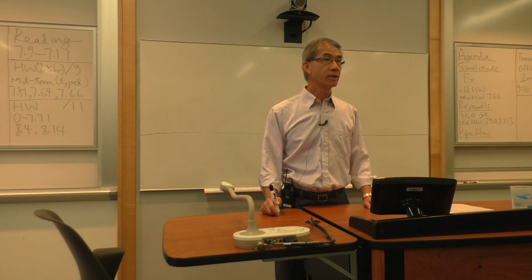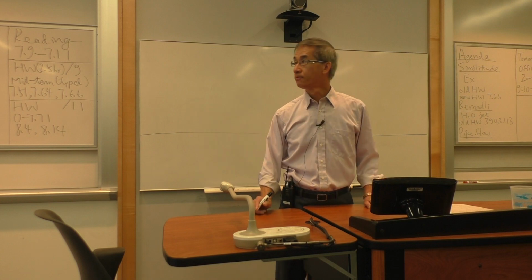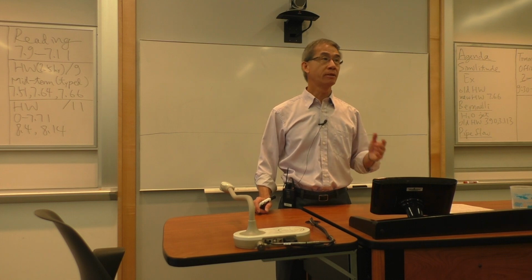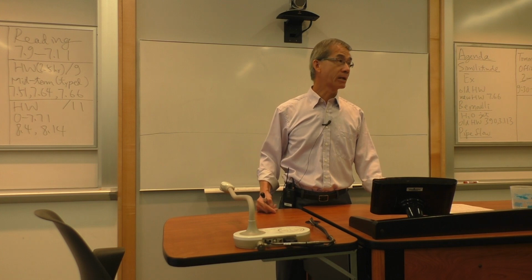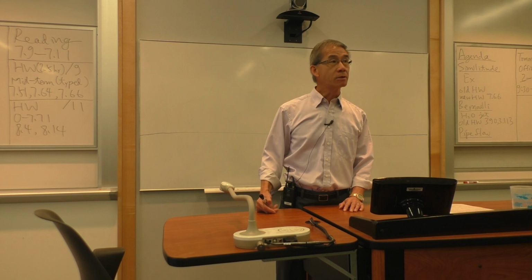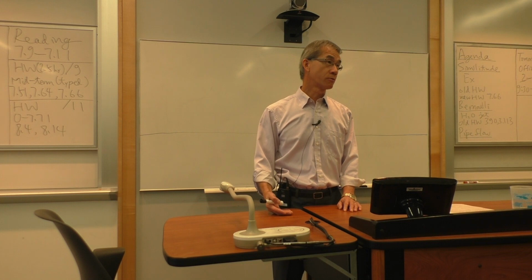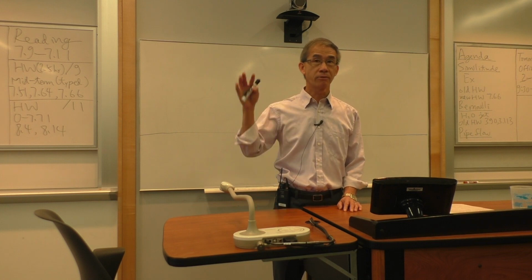And we formulated the dimensional analysis. We now have what we call a drag or force coefficient, can be drag coefficient, can be lift coefficient. And we see how it comes about by inspection. No more wasting time with exponents A, B, C and a three-unknown type problem. And then that's purely a function of Reynolds number. Any questions on those? Big picture, 30,000 feet looking down.